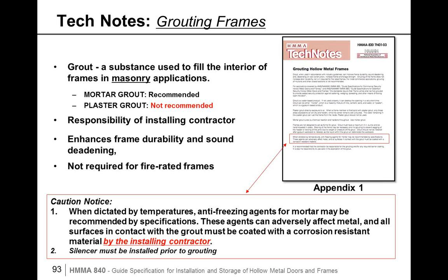Now, the grouting of the frames does help in some areas of durability and sound deadening, but it is not a requirement of masonry frames, nor is it a requirement of fire-rated frames, as I said earlier. The big cautionary note is in areas of the country where the frames are being installed in lower temperatures, freezing agents are added to the grout.